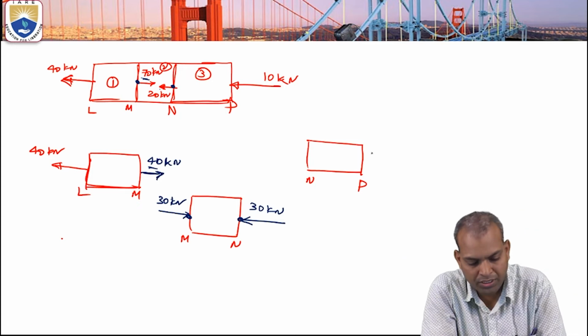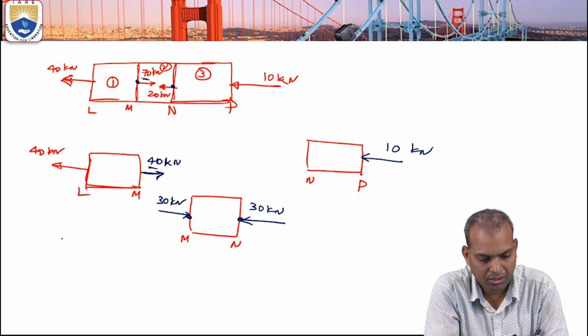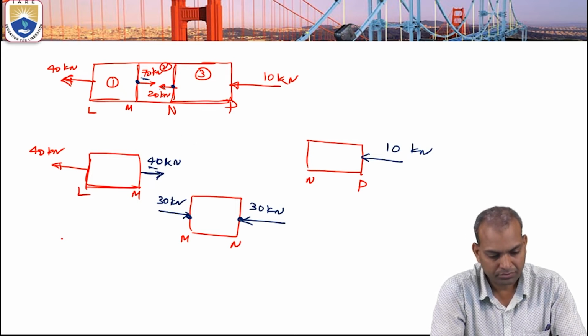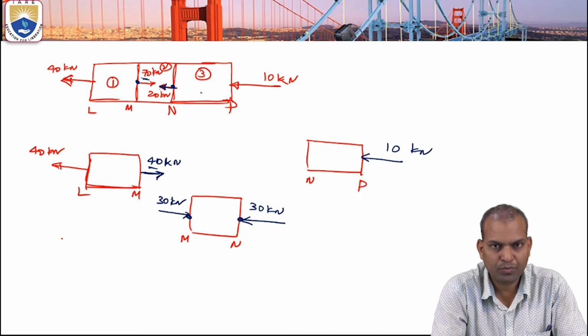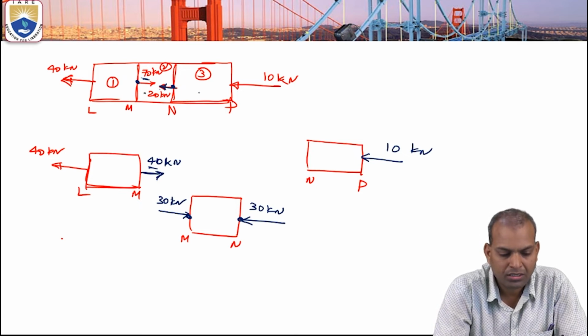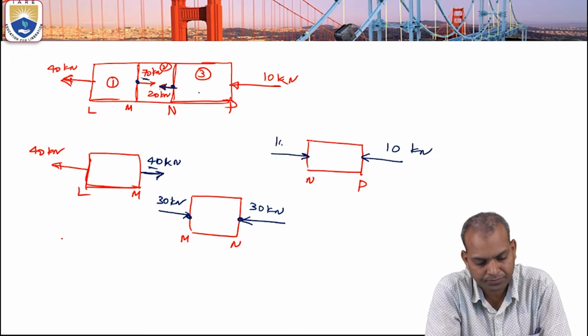Okay. Now P side is 10 kilonewtons. Now it is 20 compression. Then what will happen? 30 minus, it is a tensile on the body 3, compressive on the body 2, on the section 2. So 30 is a compression here. 30 minus 20, 10. 10 becomes compression.